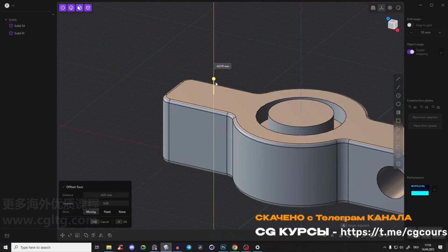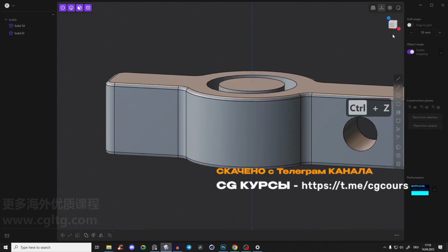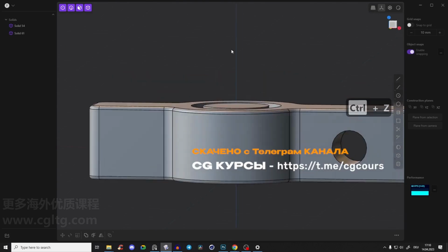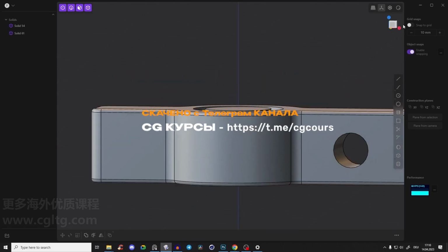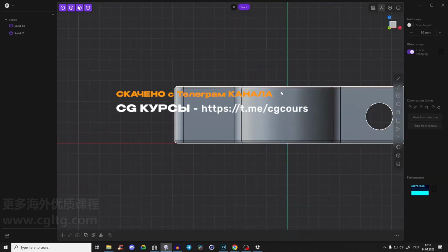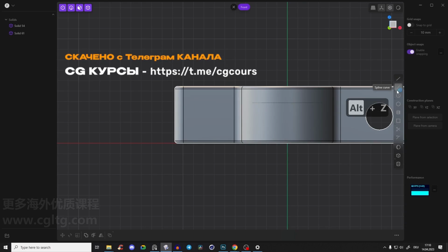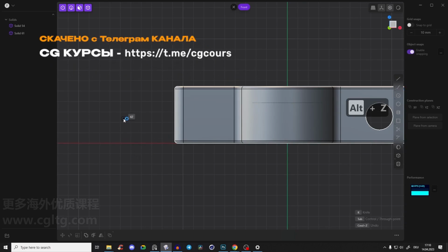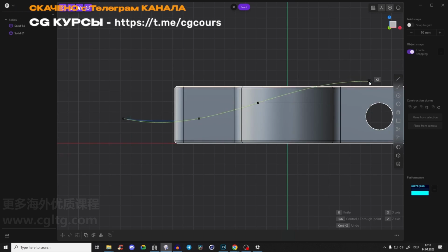So you can, for example, select this edge, but everything goes down. So for that, you can just cut the body again with the edge, and you can create a line like in Photoshop or in Illustrator as you like it. So if we press here this spline, you can just create 1 point here, 1 point here, and just something like that.